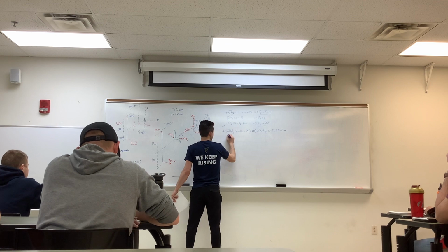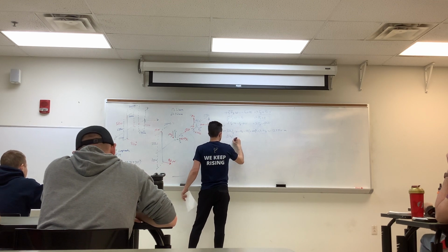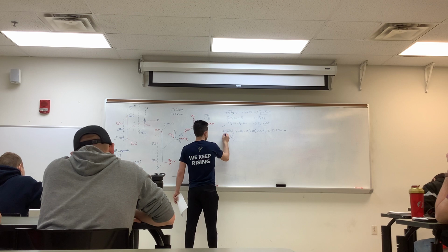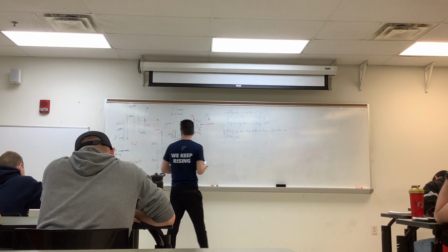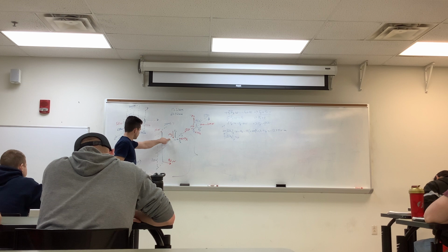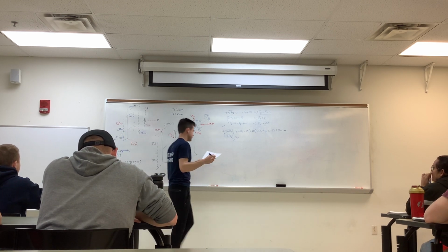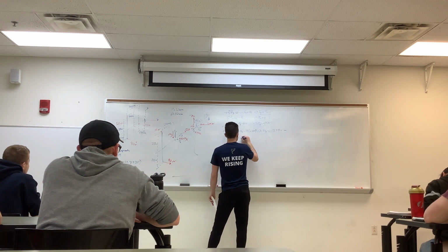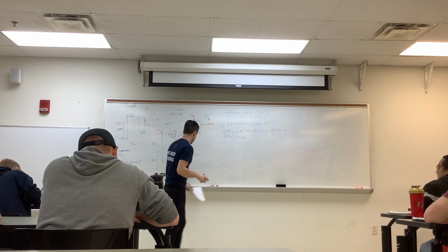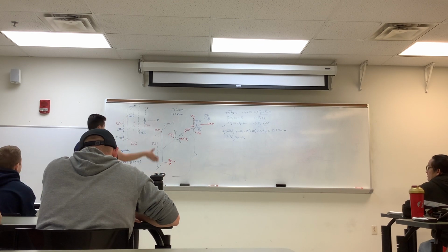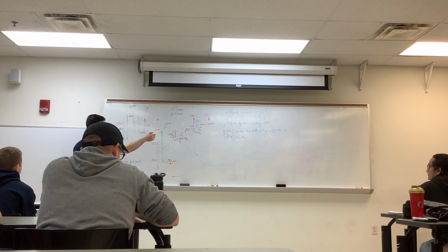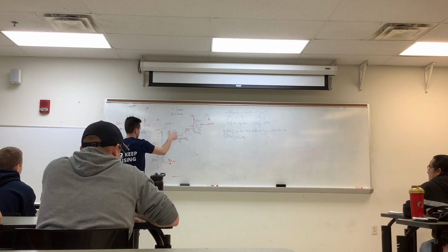Next, I'm going to do point O with respect to the y-axis, just positive is upward. Moment about y opposes what we assume to be positive, so negative My. Now again, using the right-hand rule, putting our thumb along where our axis is, curling our fingers, what causes this to rotate about that point O? This 55 newton force, since it's acting along the plane, doesn't cause any kind of moment.